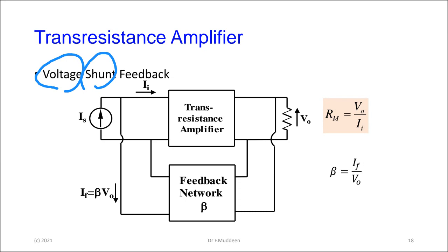If I ask you, like in a quiz question, what type of amplifier is a current series feedback amplifier? Current series: current means I'm sampling current, series means I'm feeding back voltage. So current on the output, voltage on the input, therefore that's a transconductance amplifier. It's an easy way, when you're reviewing this stuff, to look at the name and visualize it with a particular circuit. Sort of a mix and match here.